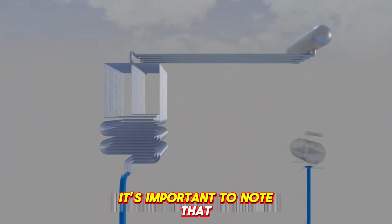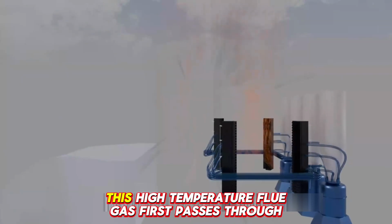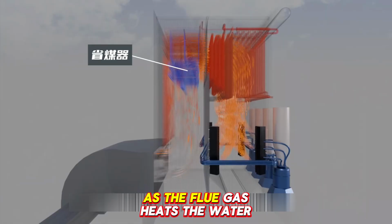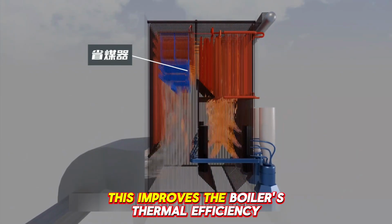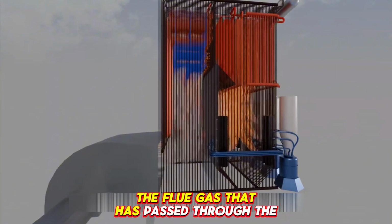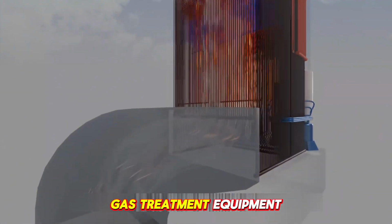It's important to note that the boiler's combustion produces a large amount of flue gas. This high-temperature flue gas first passes through the economizer, which preheats the water inside it. As the flue gas heats the water, its own temperature also drops. This improves the boiler's thermal efficiency. This is the fundamental reason why an economizer saves fuel. The flue gas that has passed through the economizer then travels along the pipes to the flue gas treatment equipment.